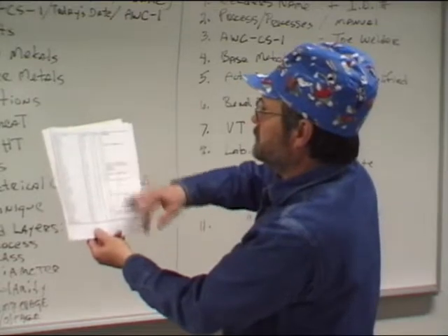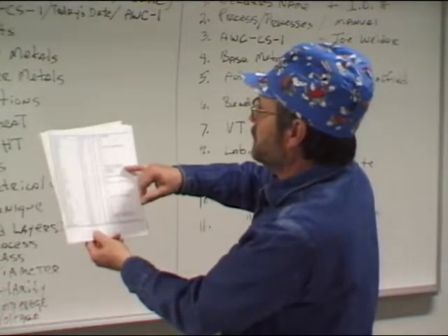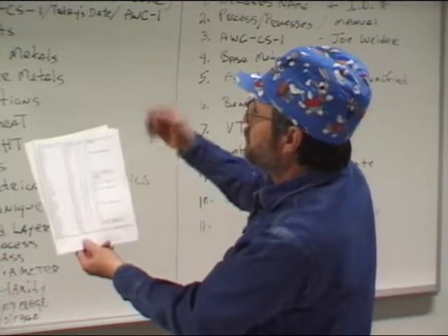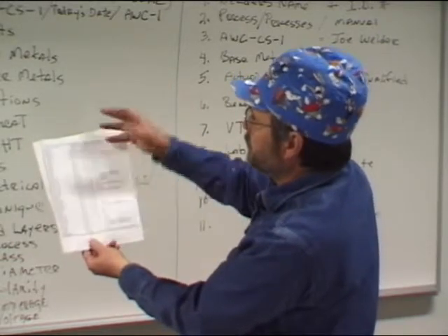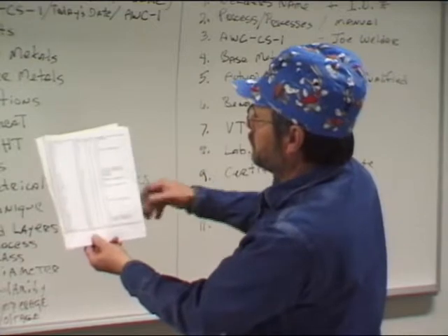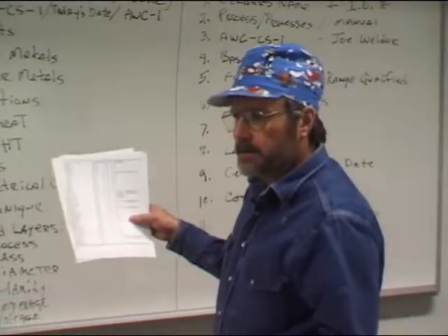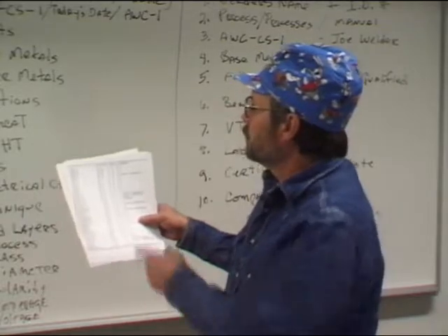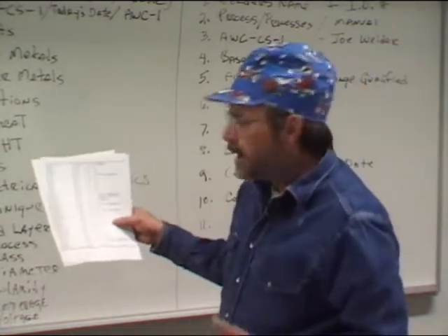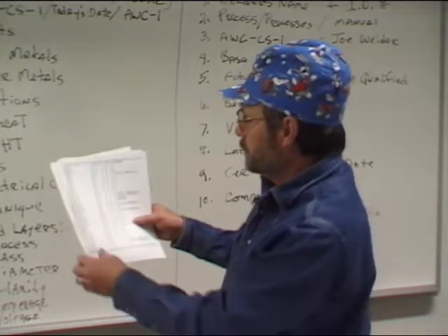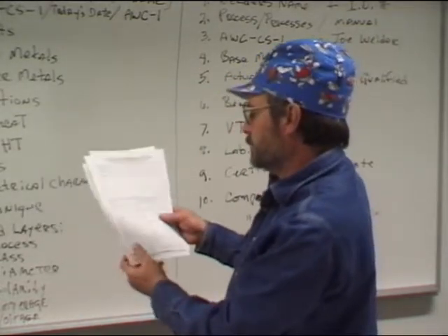Now you see that they have some different ones in here, such as verify chemistry, or here it says chrome, nickel, and copper. So it changes. So it's 1, 2, whatever. And it also changes what the type of a filler metal it is. For example, a bare wire would be a 6. Covered electrodes are typically a 1, but not necessarily all of them.